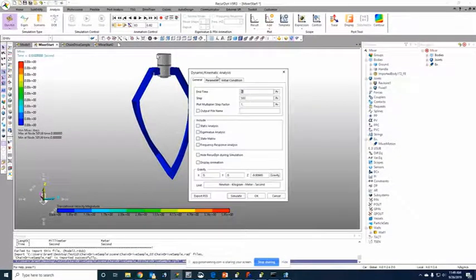All you do is go into this, run the simulation in RecurDyn dynamic kinematic, change the simulation parameters as you want to, and then all you do is click the simulate there. And this simulation takes about 30 minutes to run.